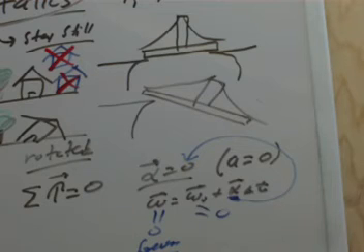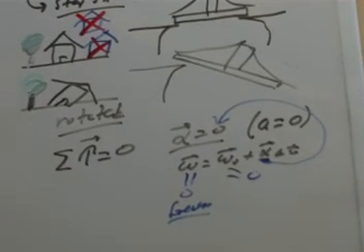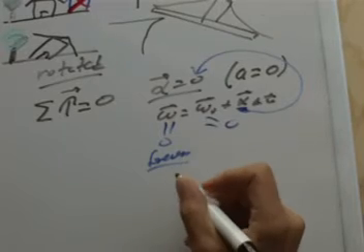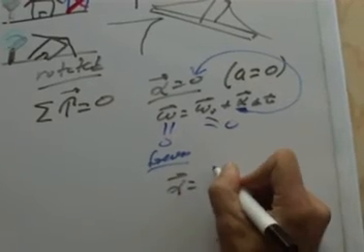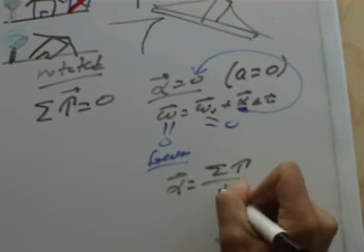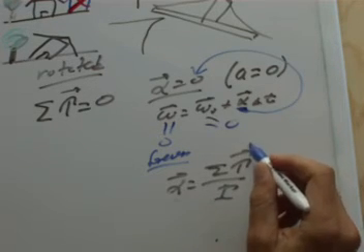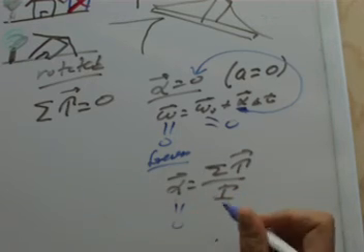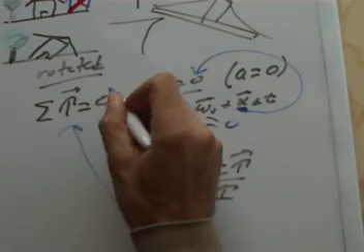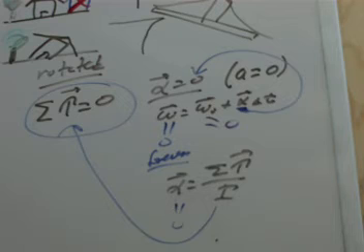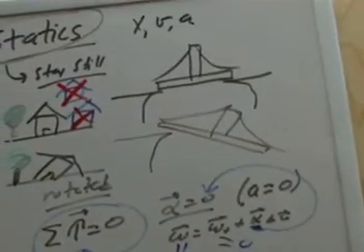So we're just ensuring that alpha is equal to 0, and also we're just going to remember this simple relation, sort of the Newton's law version of this, that alpha is the sum of the torques divided by the moment of inertia of the object. That's what alpha is equal to. And so if we want alpha equal to 0, we can solve for the sum of the torques. And indeed, if alpha is equal to 0 right here, then we are left with this condition right here, which is the last one we need to solve statics problems. So there you go. There's your setup for solving statics problems for you. Those are the 3 guiding equations you'll need to solve statics problems.